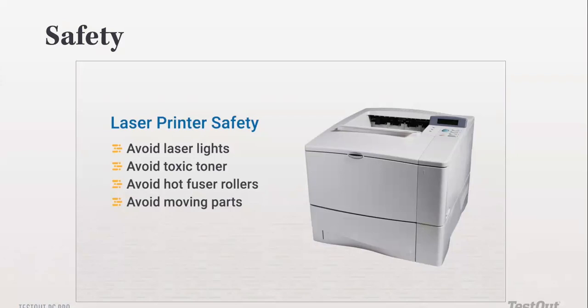There is a component inside a printer called the fuser rollers. They are responsible for applying heat on a paper so that when ink touches it, it sticks. They generate a lot of heat. So while you're servicing this component, make sure that you unplug the printer from power for a period of time so it cools down before you do anything on it. Because if you work on a printer that has its fuser roller still very hot, you risk getting hurt.